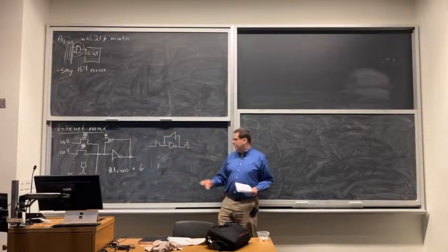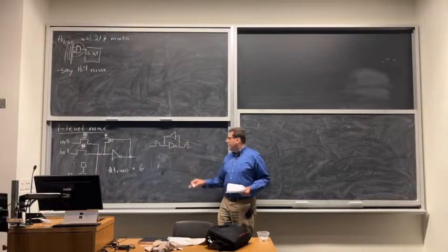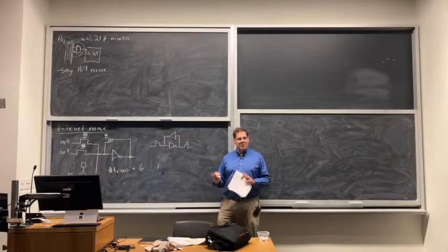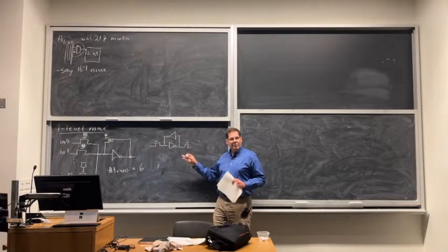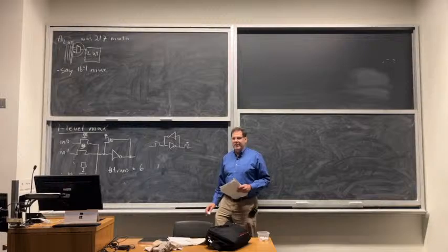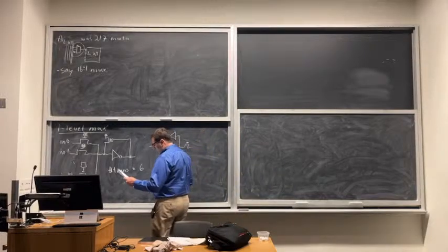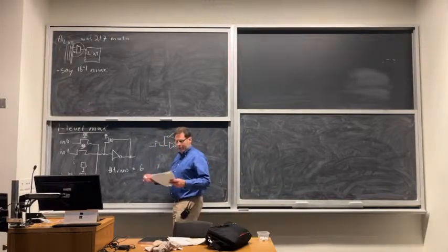Okay, this is usually a very optimized layout, so I'm going to assume that all of these are minimum size. You have to make the pass gates a little bit more powerful, but the layout's so optimized, I'm just going to ignore that and say it's 6. Well, it is 6 transistors. I'm also going to assume they're really small.